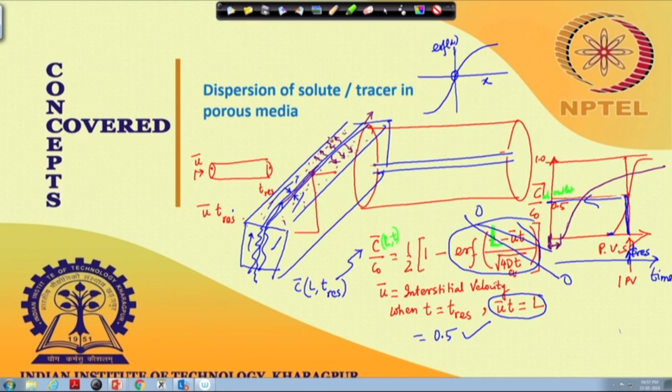The jet is moving at a very high velocity, but as it goes through the tank, the jet is mixing with the fluid already inside the tank, and still it is reaching the outlet, and I am collecting it from the other side. I will find that the fluid I am injecting will definitely be much diluted. So that same effect, here also there would be diffusion taking place. So this concentration would be diluted. It would appear very fast, but then it turns, and probably it will reach some value of 0.6 or so, and beyond that it starts tailing.